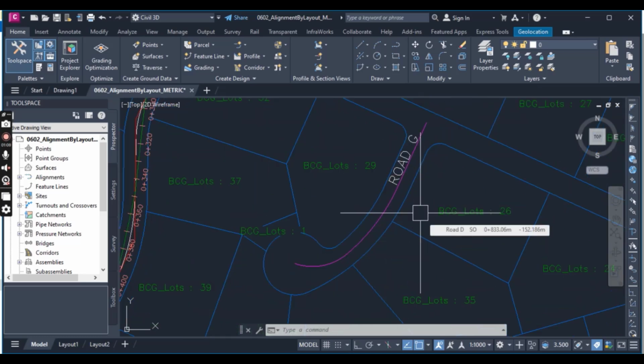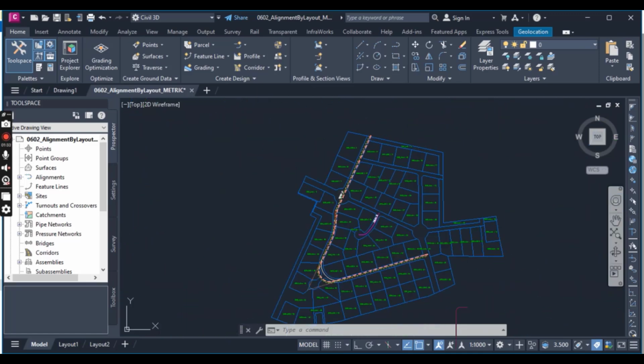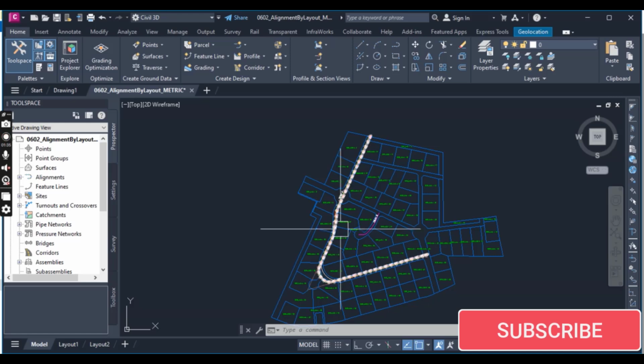It's worth repeating that when creating Civil 3D objects, it is good practice to get something in place and then refine it. With other packages, you did not want to define the object until it was fully designed. In Civil 3D, you define the object in a preliminary state and then refine your design.